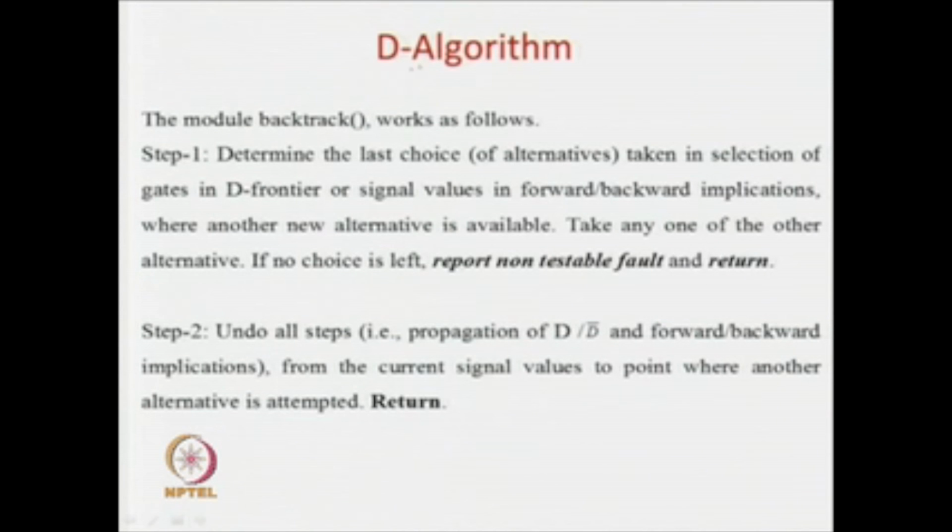But as I told you, there is some backtrack. So, what is meant by backtrack? This slide elaborates what a backtrack is. Backtrack means, for example, there is a clash: you wanted the signal value to be 1 by backward implication of the J frontier gates, but for some reason it has to be something else in some other case and so forth. In this case you have to backtrack and try other alternatives.